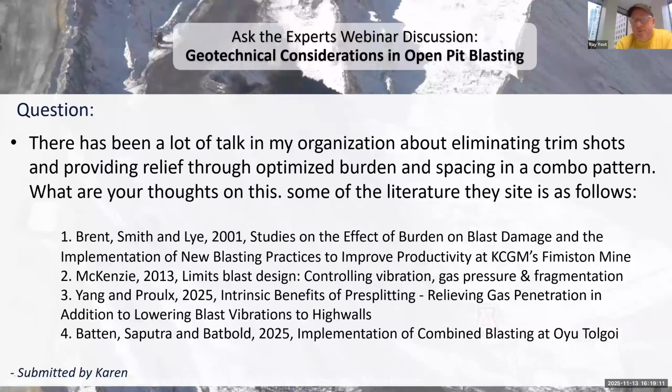But go ahead, Phil. Yeah, just speaking as a member, I sit on several geotech review boards, or GRBs, which I assume a lot of the people who are involved in this course are aware of, because they are subject to them once every year. But one of the problems I see is that there's a real push to believe that you can still control the vibration at the wall effectively with big blasts and avoiding the trim shots.